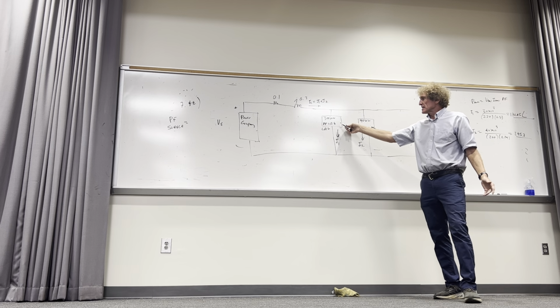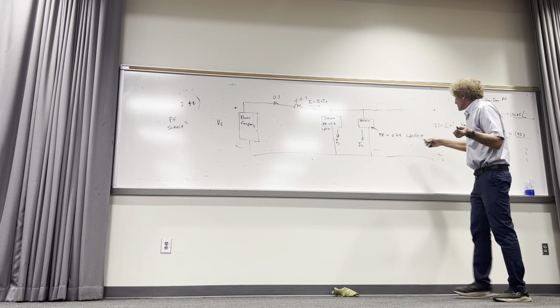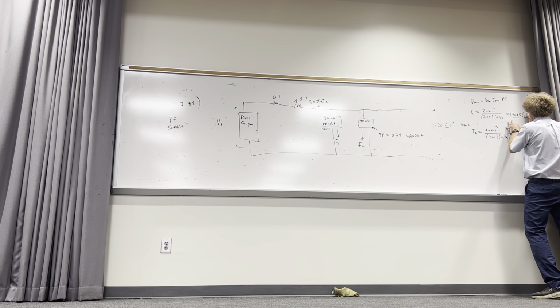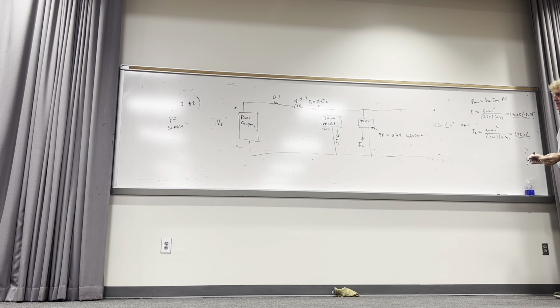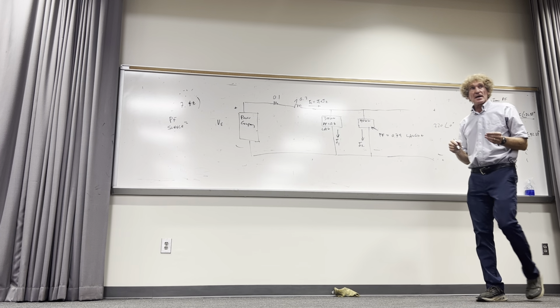You know what I'm going to do is take the inverse cosine of 0.8, which is about 36 degrees, right? And it's lagging, so it's behind the voltage angle. The voltage angle is 0 degrees, right here. So this is going to be minus 36 point something degrees. What is it? Minus 36.87 degrees. What about this? Take inverse cosine of 0.74. Anyone? 42.27. Minus 42.27 degrees. You'll notice magnitude and angle.